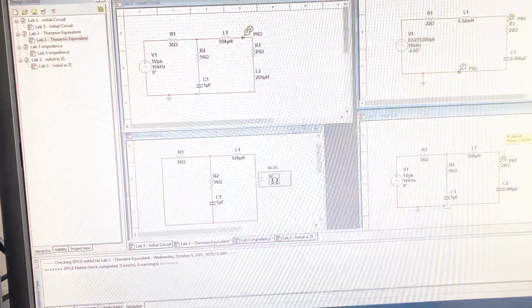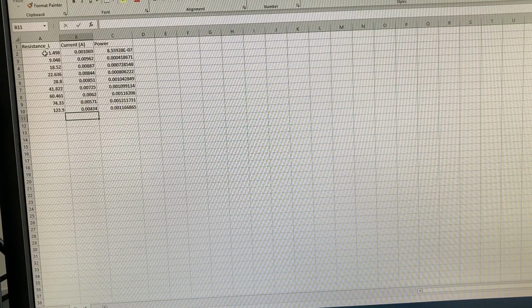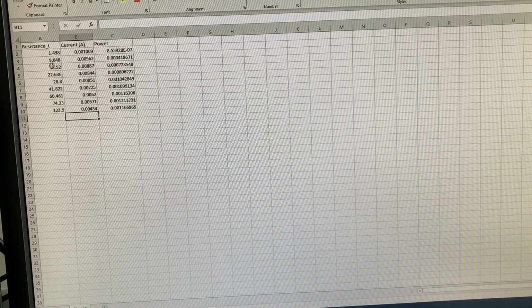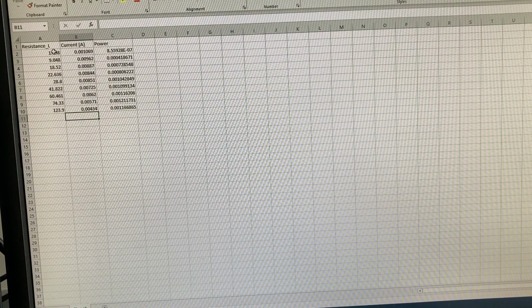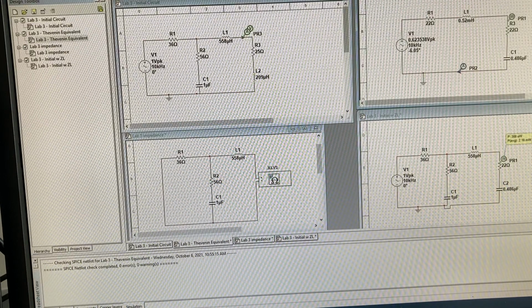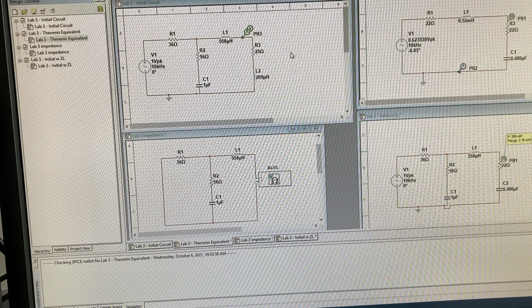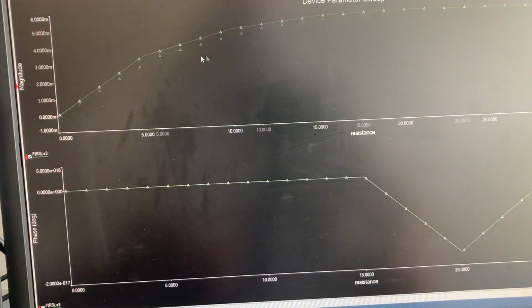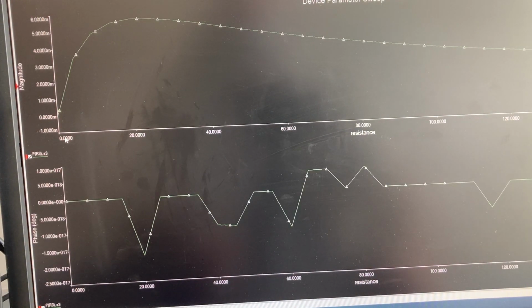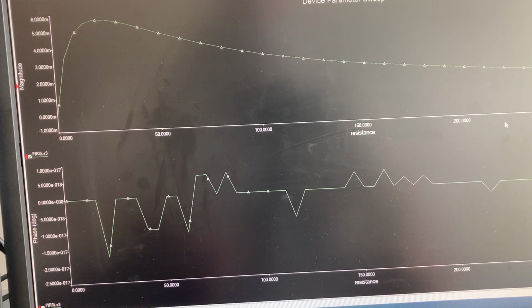And basically what I want to do is just take a series of resistance measurements. Start on the low side. So the same way the parameter sweep here is plotting the resistance values from below my maximum up to some value. Now you probably don't need 300. You just kind of want to see that the peak rises and falls back down.